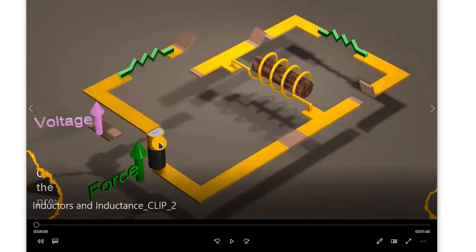In this video, we have a source of electromotive force. That is a cell. That one is pushing a current through the whole circuit. Indeed, this is the positive terminal and this is the negative terminal. The negative terminal has the electrons. Electrons will have to flow in this direction. But conventional current, we take it that the positive charges will be flowing, even though we don't see positive charges actually flowing. But we take it that conventional current flows from the positive terminal to the negative terminal.